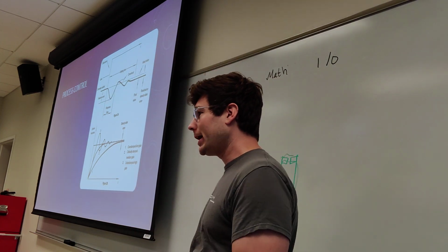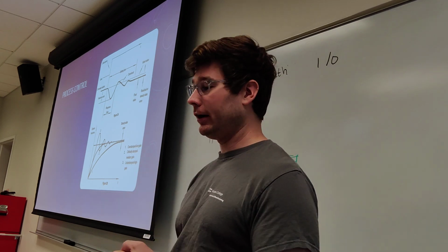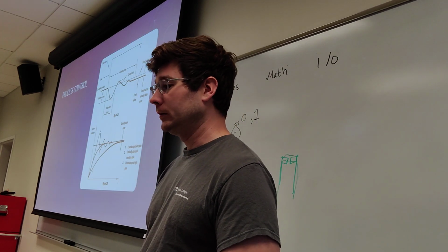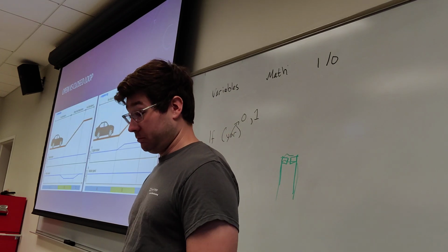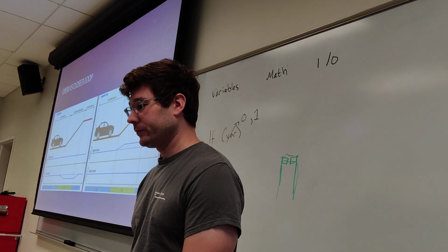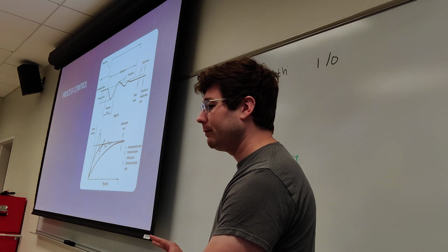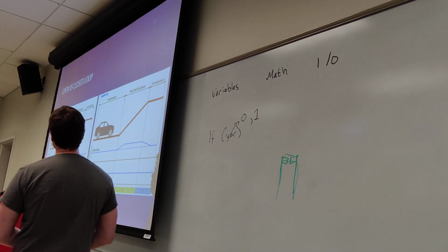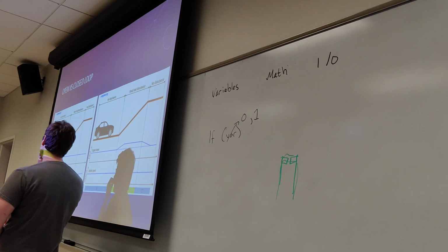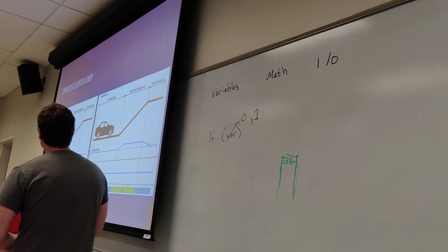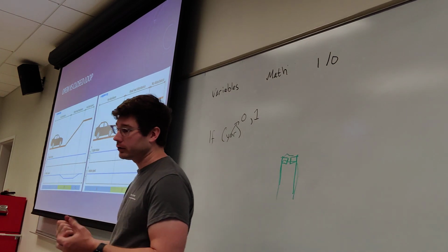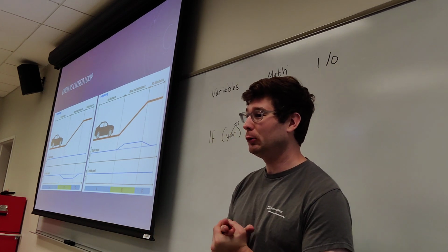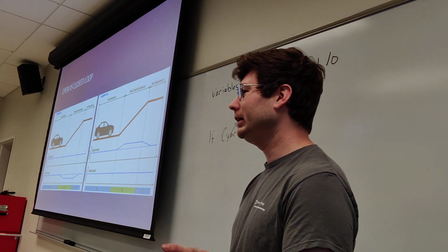How accurately can we track those changes, and how can we respond in order to make our system do something? Okay. There's many different ways that we can do this, but there's two primary kinds of process control. Open loop control versus closed loop control. The reason why there's two different types of control is essentially cheapness. Open loop controllers don't need as many sensors.